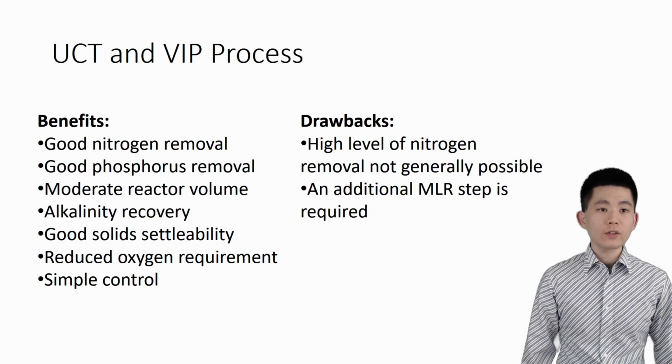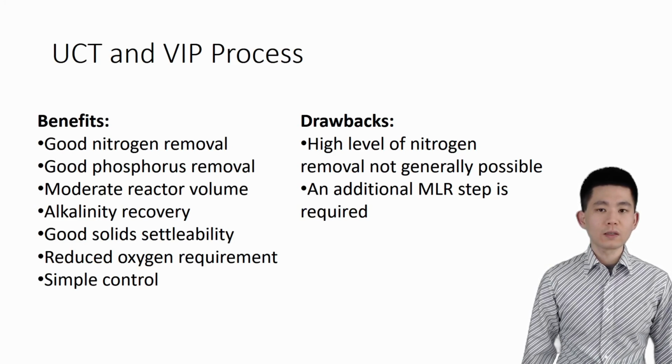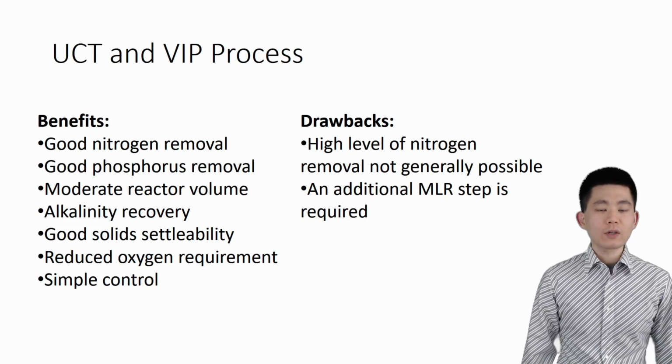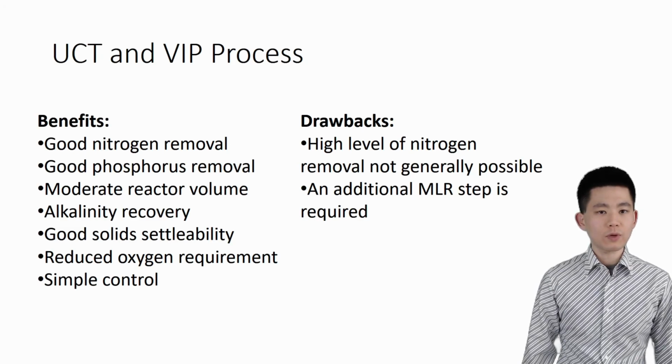The recirculation design ensures high phosphorus removal efficiency, but like MLE, the unrecirculated nitrate is discharged. Therefore, it generally cannot achieve a high level of nitrogen removal. Also, the addition of recirculation lines can consume a lot of energy and can decrease the reaction rate by diluting the substrate.